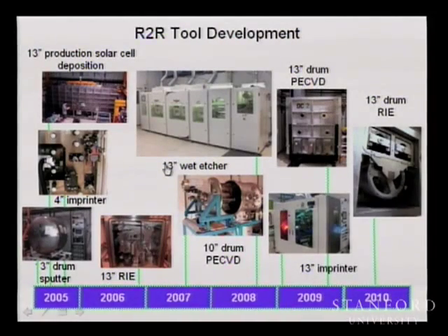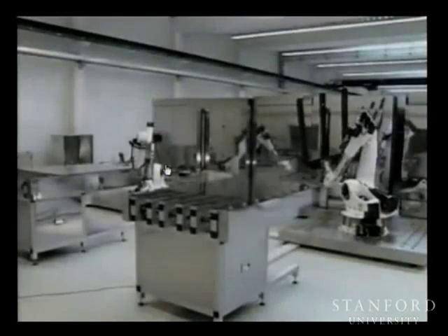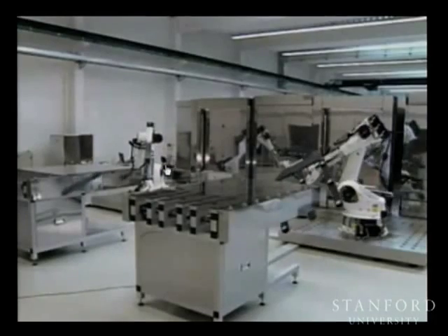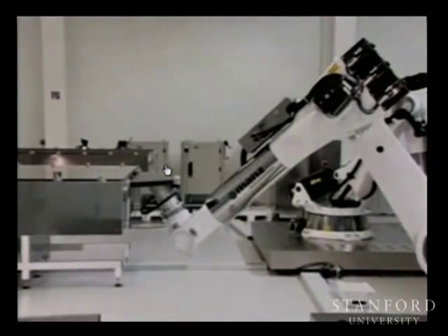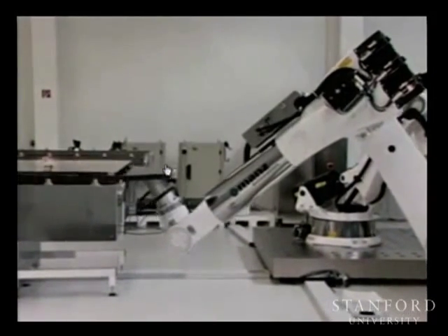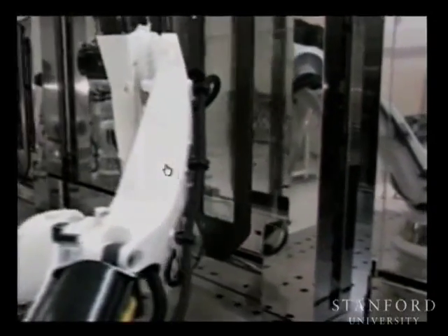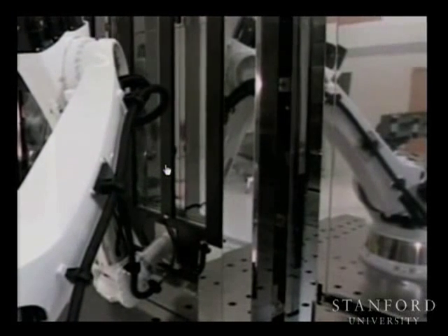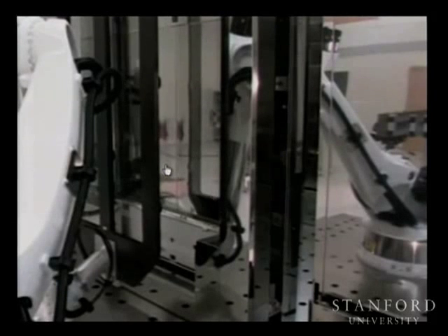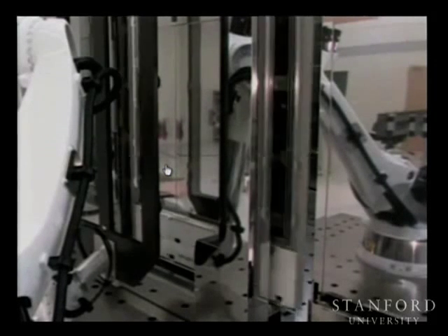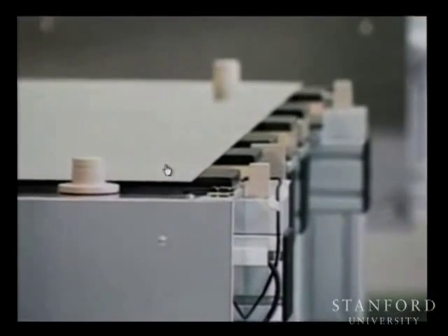All these things do. By contrast, this is KUKA, a robotics company that makes a lot of this stuff. I think this may be Gen 10 glass. I'm not sure. But it's amazing when you think about what they're doing and how difficult this really is, to take that piece of glass and move it around. And if you look at this carefully, after it places, it almost looks like the video hangs, but really what they are is settling transients. And if you look at the reflection of that piece of glass, you'll see it starts shaking around. And again, when they pick it up, you can see the edges of it all flapping around.